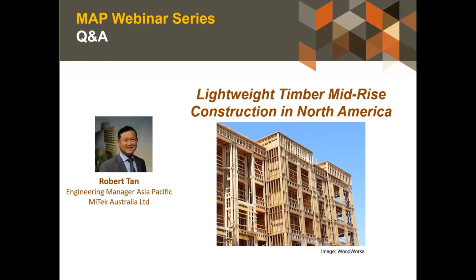The other thing is that you'll notice I put in one picture only of a gap. They do introduce a lot of gaps in between sheathing and sometimes even within the floorboards. They try and create some gaps so that it takes up some of the movement and shrinkage as well, so they don't have unnecessary contact. And there was one more thing I was going to say. I've lost it now because I've been talking so much. I guess we're mainly focused on the timber construction side, but even the plumbing and things like that do have connections that allow for the movement to occur as well. Thank you, Dean. That was what I was thinking of.